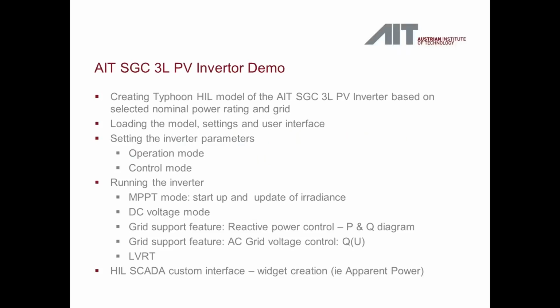So in today's presentation, we'll cover the following points: how to create a Typhoon HIL model of the AIT SGC 3-level PV inverter by selecting nominal power and type of grid, how to load these models and settings, then we'll demonstrate how to operate the inverter by setting inverter parameters, how to change operation mode and control mode that I was talking about a moment ago, then a demonstration of the inverter in action: MPPT mode, DC voltage mode, grid support features, LVRT, and finally our user interface, and we'll show you how easy it is to make your own custom interface.